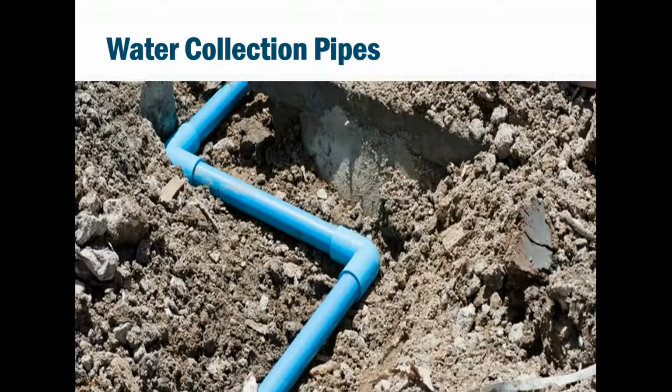Structures like this in the base course do not negatively affect the overall strength and stability of your paver system. So you can know you can install them and not worry about losing strength.